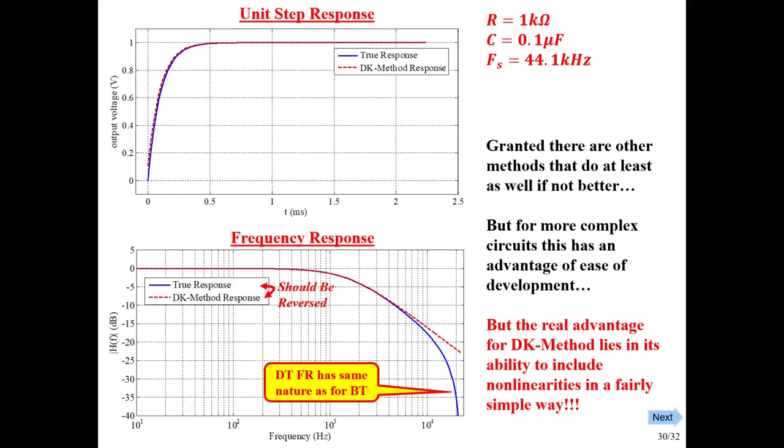So you can see the frequency response mimics the RC filter's response very closely all the way up to 1,000, 2,000, 3,000, 4,000, 5,000, 6,000. Look, guitar signals have very little content above 5,000 hertz. So over the range that a guitar signal has anything significant, this is virtually indistinguishable from the actual RC circuit.